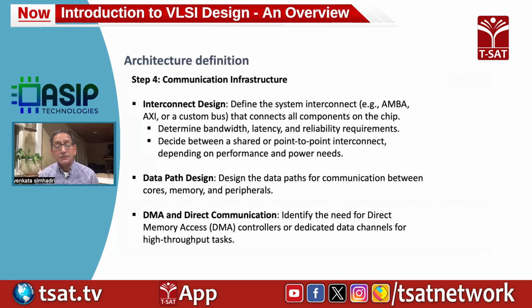And most of the chips nowadays also use off-chip DRAM memory to store your data in and out. So you may need a DRAM controller and DRAM interface on your chip. You need to define that as well.